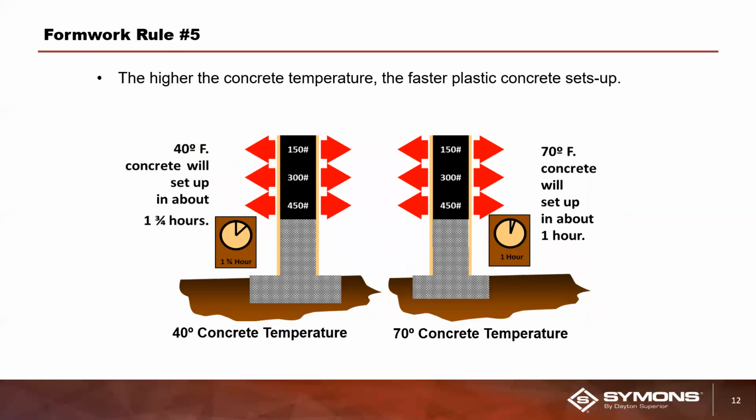Temperature does play a factor in all this. All these numbers are basically based on a temperature of 70 degrees Fahrenheit. Typically, if it's colder, it's going to be a little bit longer for the concrete to set up, versus if it's a little bit warmer, it's going to set up a little bit faster.